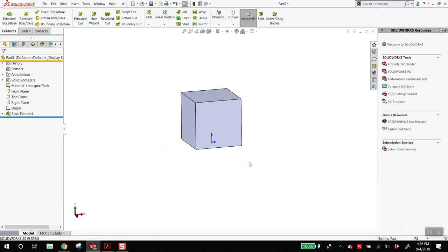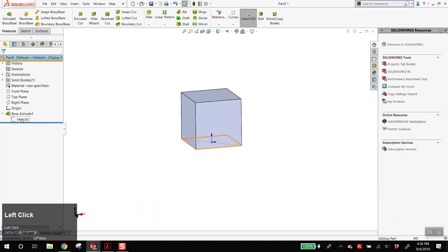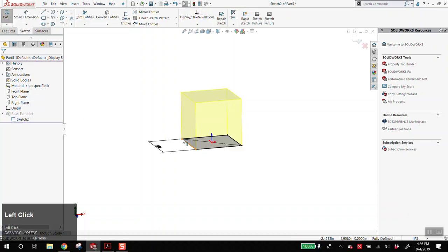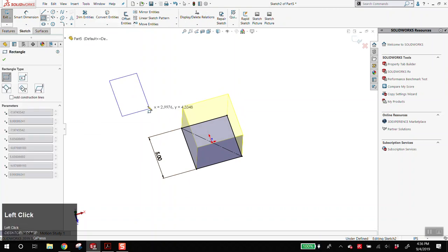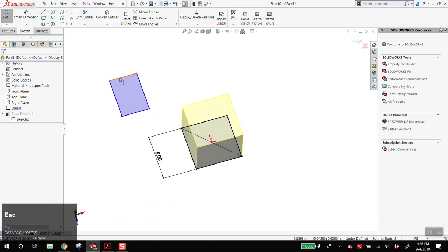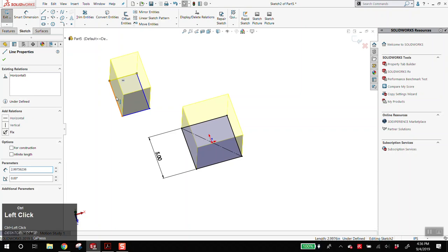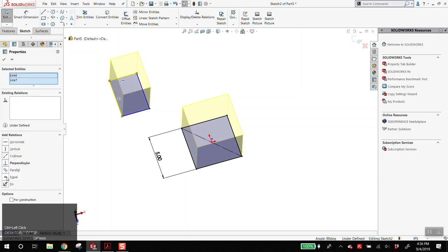Yes. When you go to make a perfect cube, do you hold down control? Is that what you do? Oh, gotcha. Yes. So I'll do this on the side here. Hit R. So in order to make both of these equal, you want to click on this, hold down Control, click on this, and that, yes, so that you're selecting both at the same time, and then say equal.